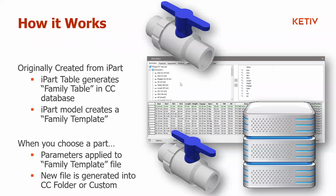Unfortunately, a lot of people have standard components, and the only way they can generate custom part numbers is to create their own library in a custom folder. They have to remember, if I've already generated a 1/2 inch by 2 inch bolt with coarse threads, to go back to the library first and see if somebody's already created one, and if not, then generate it. It just becomes a mess. So this is one of the reasons that justifies why we might want to manage and create our own custom content center library.